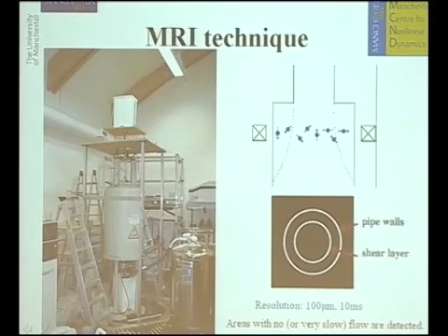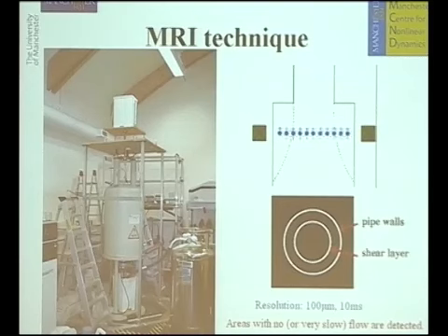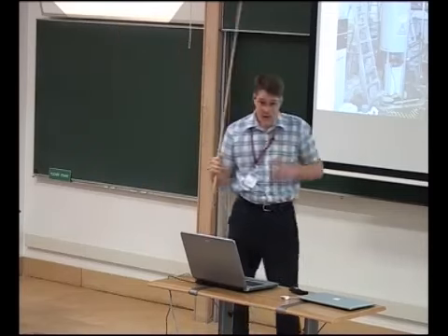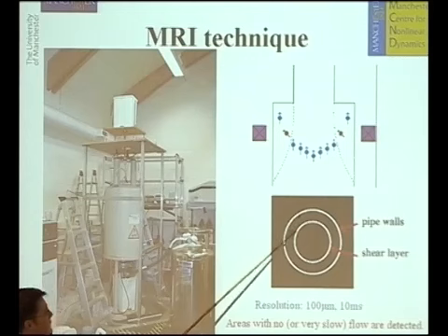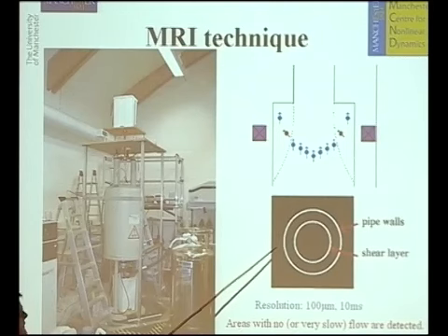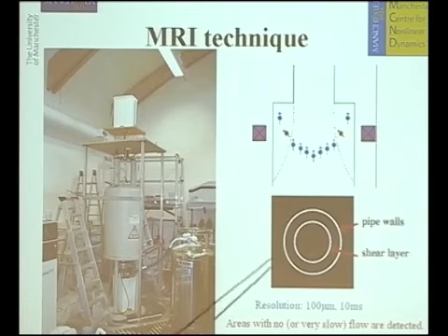So here's my expansion, here's my slab of fluid I'm interested in. Let's start that, okay. So there are all my spins by water molecules. I'm going to use a magnet to align my spins, and I'm going to use a gradient to knock these over and make them precess. So this is now my water in this slab of fluid. The flow is going to occur for a short period of time, a few milliseconds, and now I'm going to use the magnetic field again to look for spin echoes back in the same slab of fluid I was originally looking at.